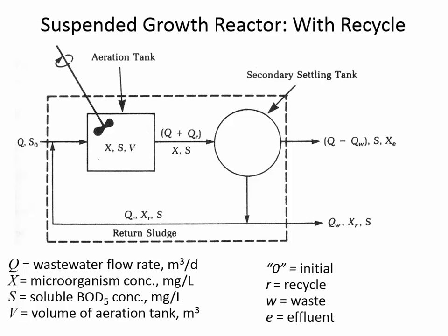Remember, this is a completely mixed flow reactor, CMFR. When the BOD comes in, it's instantly spread out. Now, they're not as efficient as a plug flow reactor. Remember, with first order kinetics, we've talked about plug flow reactors versus completely mixed flow reactors. But they're easier to operate than a plug flow reactor. And so it's more common to have an aeration basin acting as completely mixed rather than plug flow, just because of ease of operation.